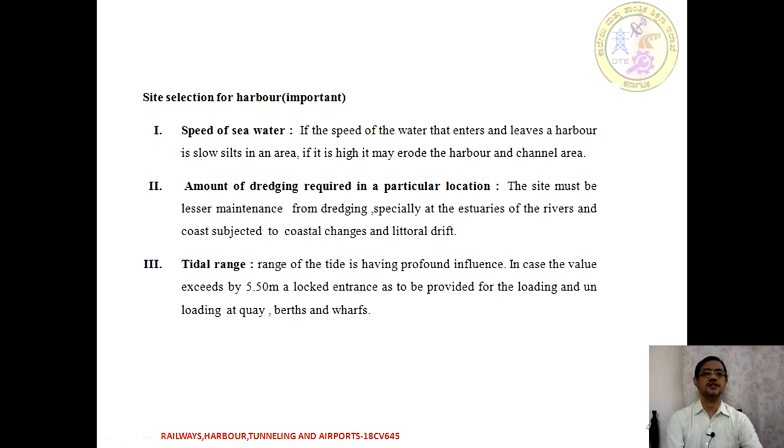First one is the speed of seawater. If the speed of the seawater as it enters or leaves the harbour is going to be slower, it results in silt or deposition. If it is going to be at a higher velocity or higher speed, it will erode the harbour and the channel area. Hence, an optimal speed has to be considered when the site is going to be selected.